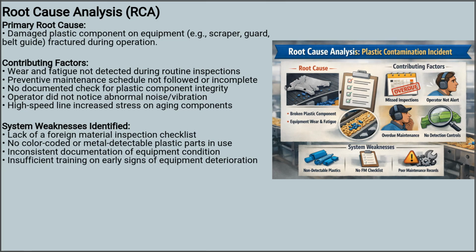The investigation found that a damaged plastic component on the equipment had fractured during operation, allowing small pieces to enter the product stream. Contributing factors included missed wear during routine inspections, gaps in preventative maintenance, and the absence of a checklist focused on plastic component integrity.